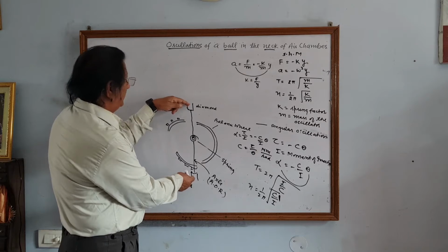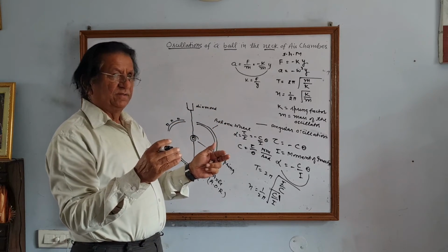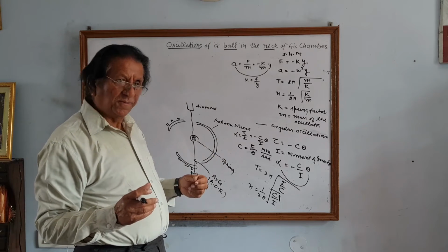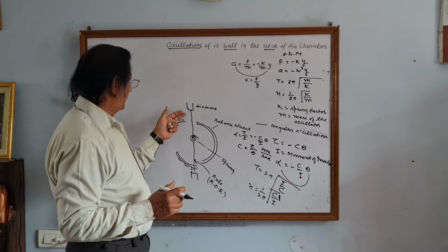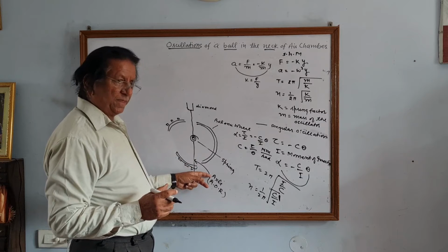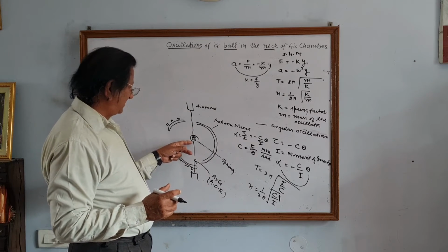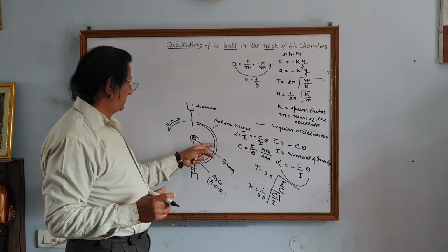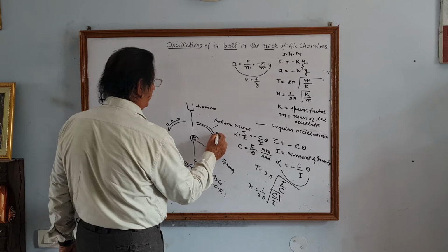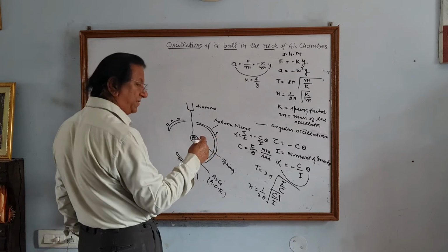Between these two diamond points, as you have a rigid support, like a spring with a mass attached, the free end has the mass attached and the other end is rigid. Similarly, these diamond points are the axis, the axle. Then here at the center there is a spring and then there is a balance wheel. The outer part is made of two different metals.